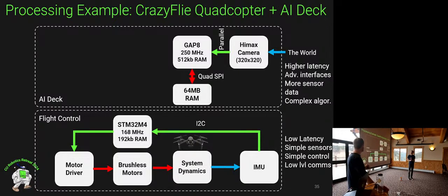And so they use a really high speed bus interface to communicate with an external RAM chip on the board. That allows them to take imagery in, store it there, and then actually do mathematics on it in real time. That's one way you can get around the bottlenecks and limitations of microcontrollers and not have to use something like a Jetson with a lot of RAM.